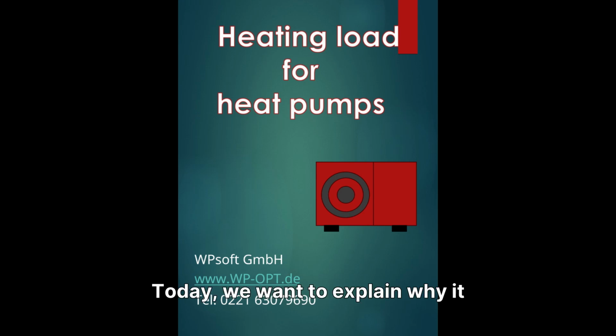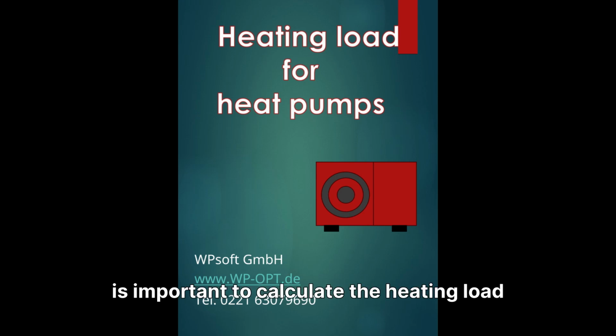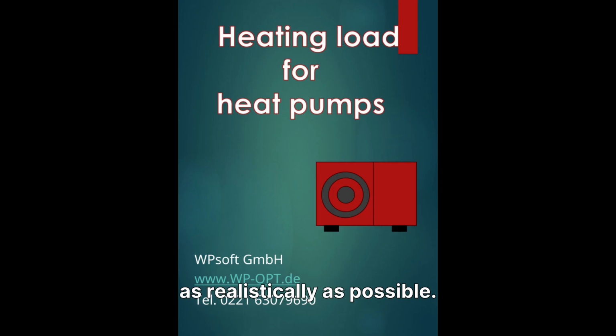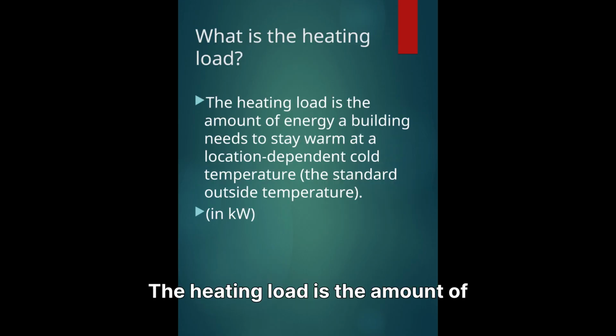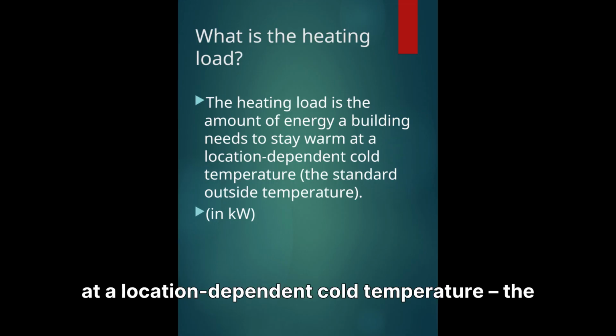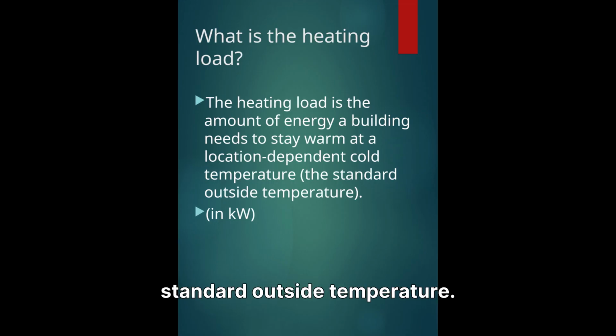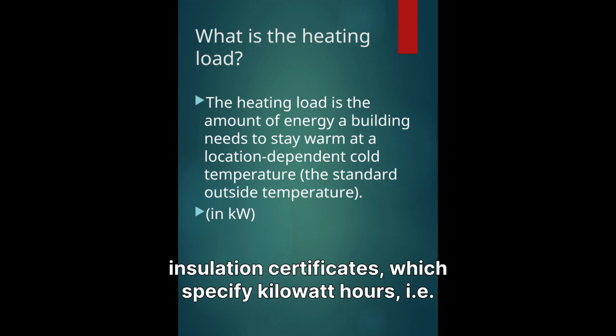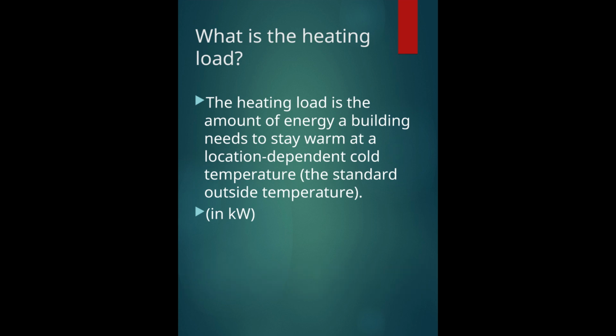Welcome. Today, we want to explain why it is important to calculate the heating load as accurately as possible, and how we can use approximate methods to estimate it as realistically as possible. The heating load is the amount of energy a building needs to stay warm at a location-dependent cold temperature, the standard outside temperature. It should not be confused with the results of energy performance certificates or thermal insulation certificates, which specify kilowatt hours, i.e., the annual requirement.